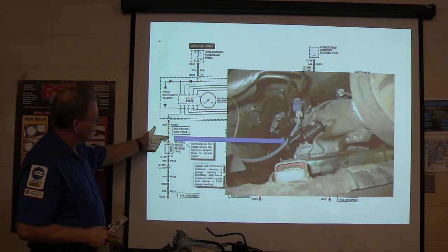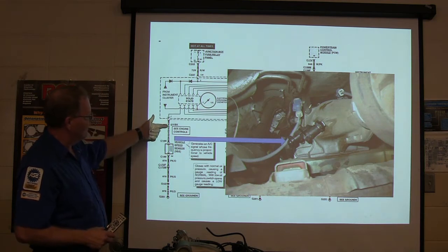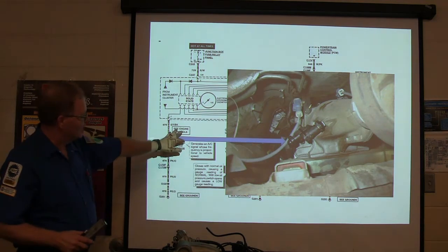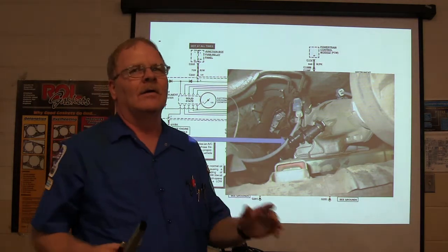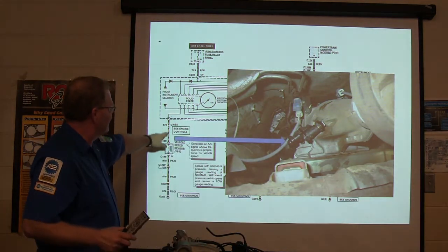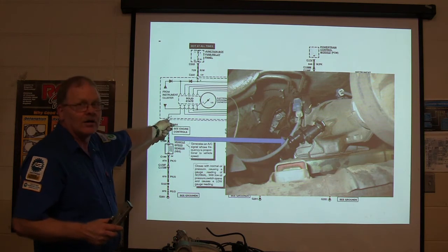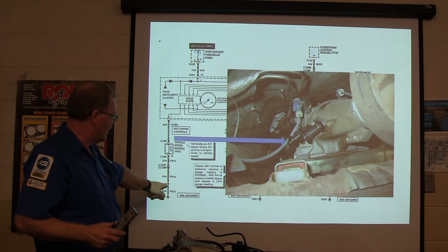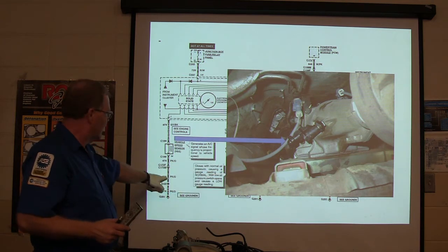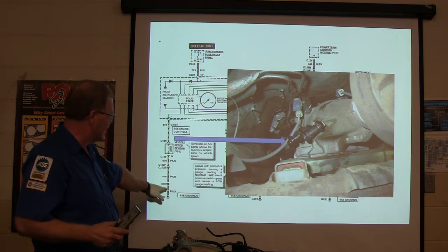On one of these kinds of schematics, if you see dotted lines right here, and you also see engine control, that means you're not seeing that whole circuit. In other words, this wire goes other places besides just to there. Now if there's a splice, you obviously got some going somewhere else too. But if it's a solid wire, that's the only place it goes.